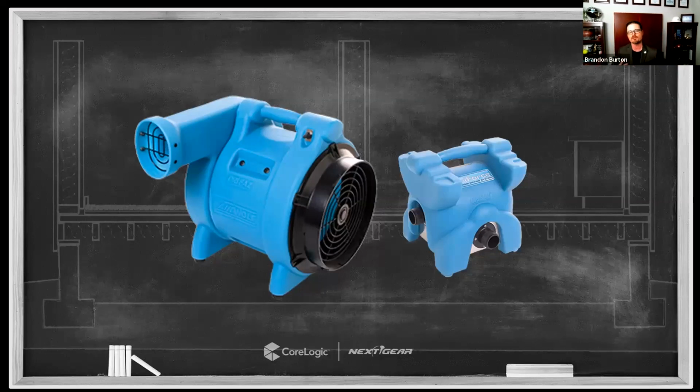So there's lots of different air movers out there that don't just produce a lot of air. They also do so well under resistance to airflow. They have a lot of what we call static pressure, the ability to force air to move through restricted spaces. And we have a lot of restricted spaces that we need to dry, right? Whether we're talking about wall cavities or hardwoods or cabinets or built-ins, whatever it is.